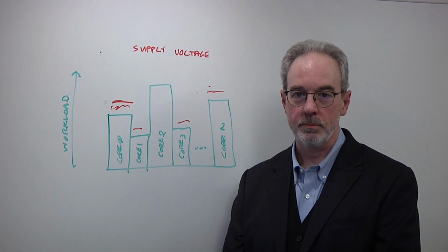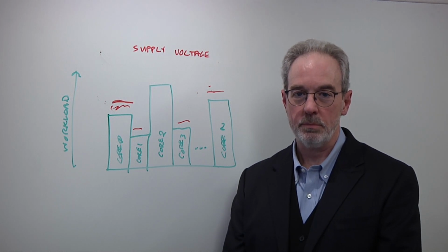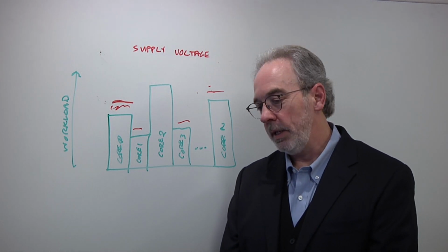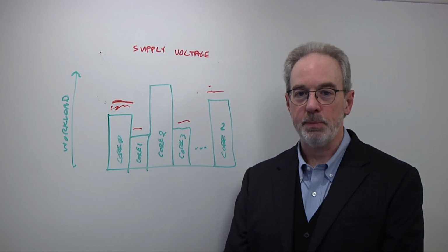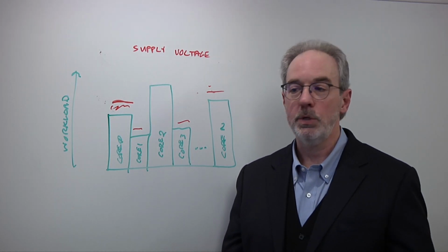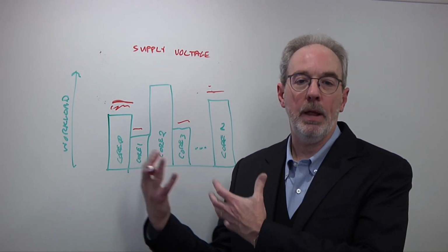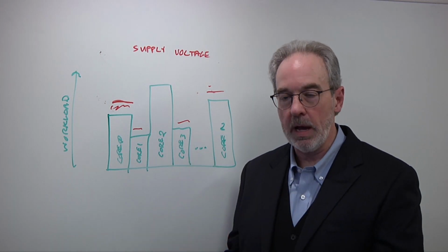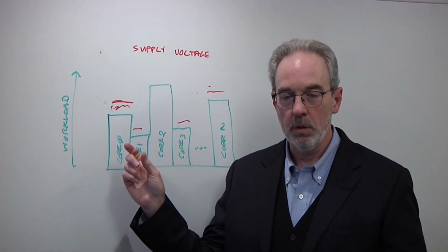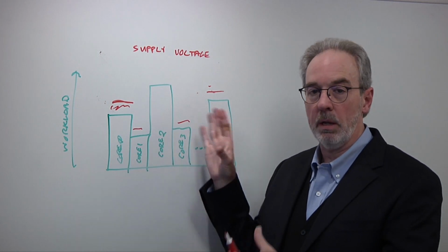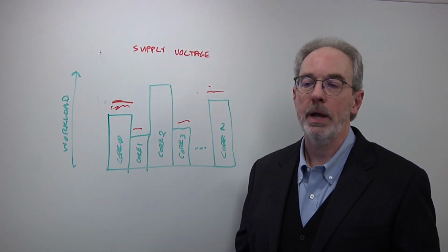So all this looks really great on a whiteboard. What does it take to enable it? Yeah, again, this is not something that's been broadly deployed because of the challenges. We talked about you can't have multiple external regulators. You've got to bring them on the die. When you bring them on the die, they have to be small because you're embedding them, again, in amongst your digital array or digital compute blocks.